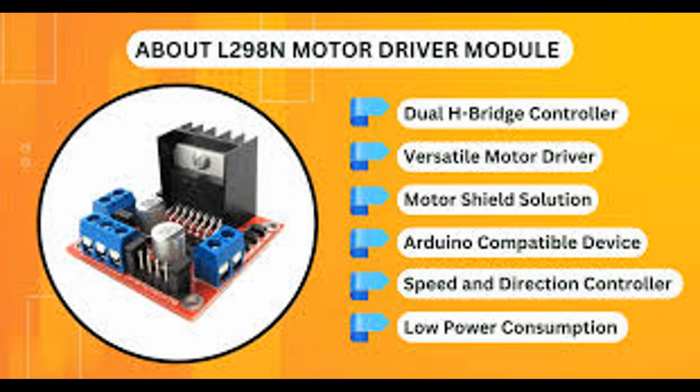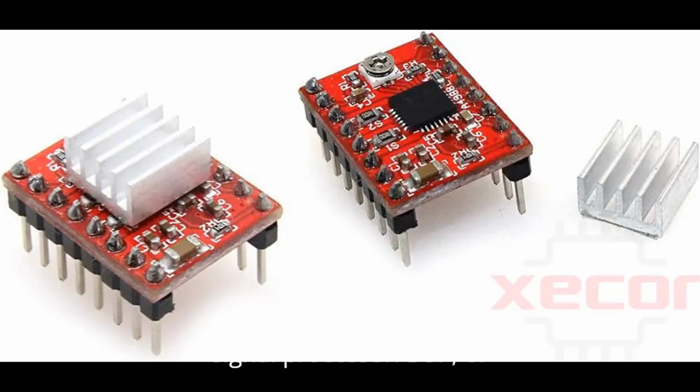6. Digital BLDC motor drivers. Function: digital BLDC motor drivers use a digital signal processing, DSP, or microcontroller-based control system to precisely manage the motor's operation. Operation: these drivers process inputs from sensors or use sensorless methods and generate control signals for commutation. The digital control allows for more sophisticated features, such as programmable motor profiles, speed control, fault detection, and real-time adjustments. Advantages: digital drivers can offer enhanced flexibility, programmability, and integration with advanced control techniques like FOC.